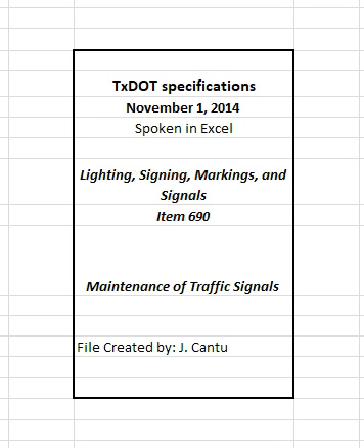4.18 Signal-related signs. Install, repair, replace, remove, or modify small post-mounted or overhead signs. 4.19 Curbs, ramps, and sidewalks. Install, repair, replace, remove, or modify curbs, ramps, and sidewalks. Secure permission to install traffic signal items before cutting into or removing curbs, ramps, and sidewalks. Replace all curbs, ramps, and sidewalks as shown on the plans. Install pedestrian access ramps as shown on the plans.